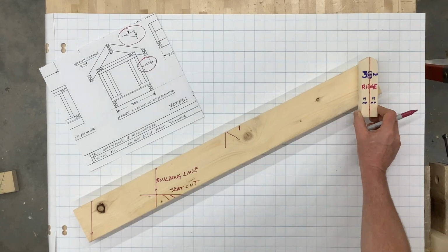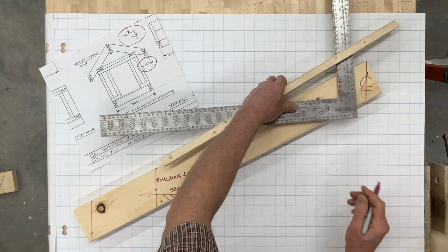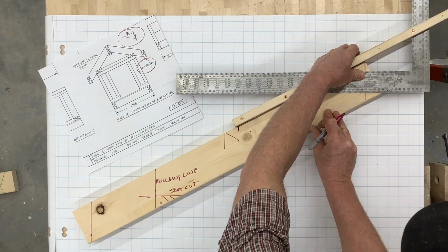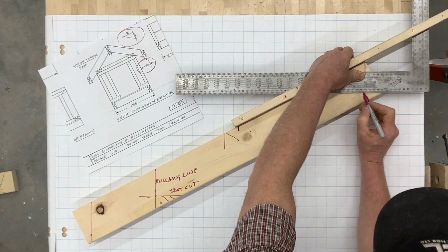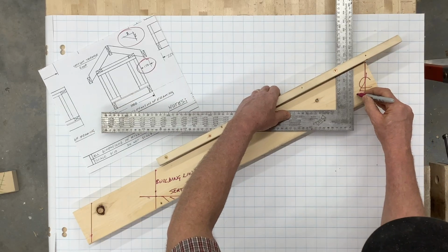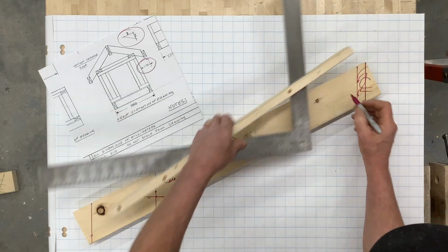Now we'll make the adjustment at the ridge. The 19 millimeter adjustment for half the thickness of the ridge needs to be measured horizontally, not along the slope of the rafter. To do that, slide your framing square fence along until any convenient measurement on the run of the square aligns with the center line. Measure 19 millimeters, put a tick mark, and then mark the plumb cut line for your ridge.